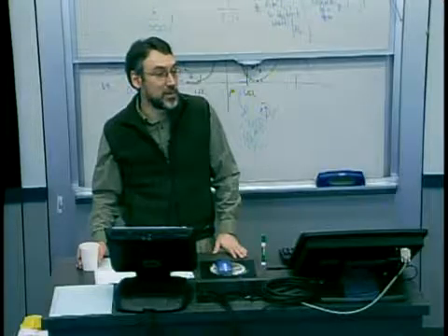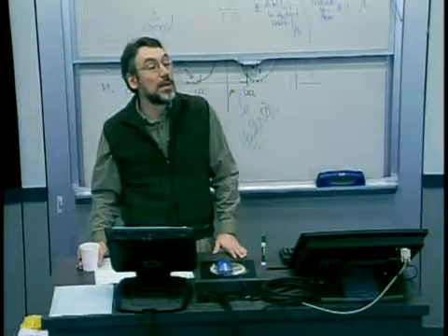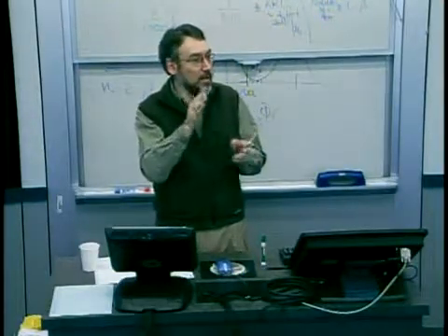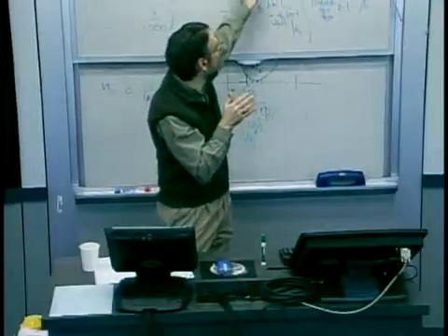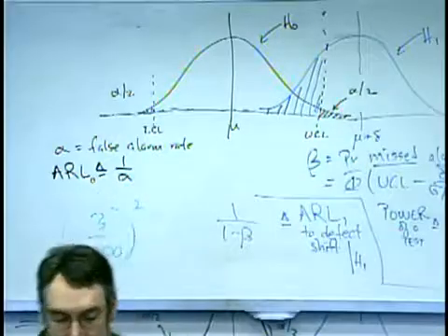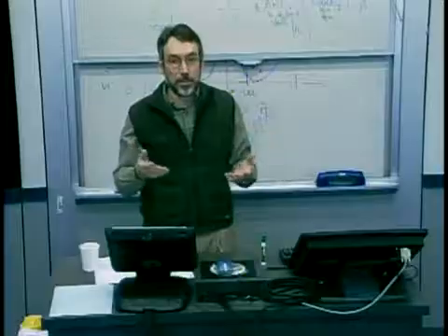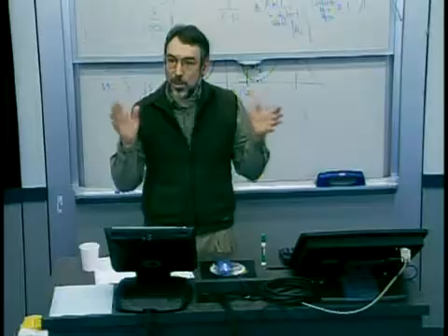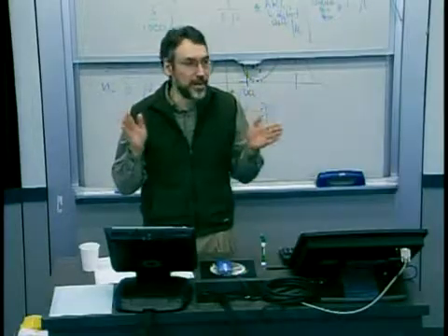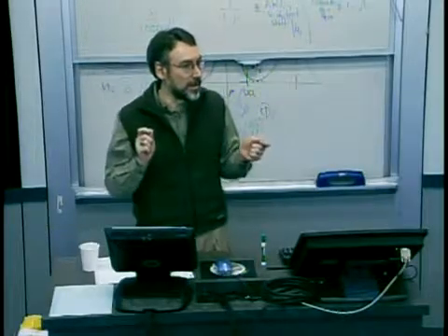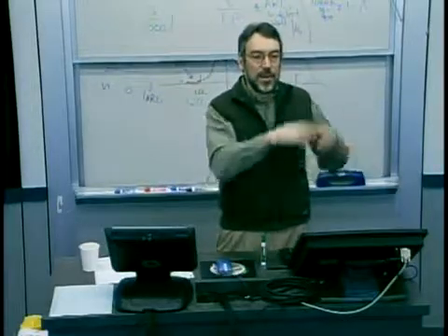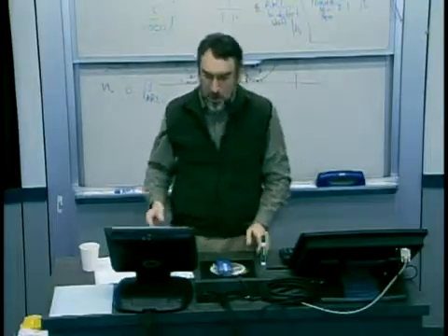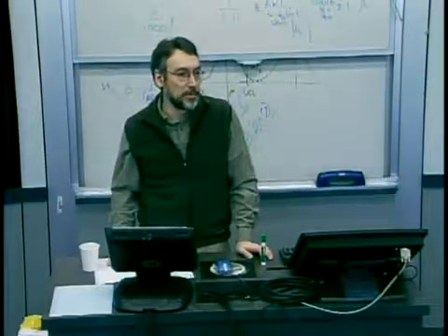Failing that, I think then you start looking around to see if maybe there's not a systematic trend. What you're hypothesizing, in fact, is that there was a shift, not a trend. And you start talking to people, looking at the equipment, talking with the operators, and ask, did something unusual happen? The whole idea is you've detected an unusual event. Might that be correlated with something else in the operation of the machine changing? So you start investigating and looking for things that might explain a shift.